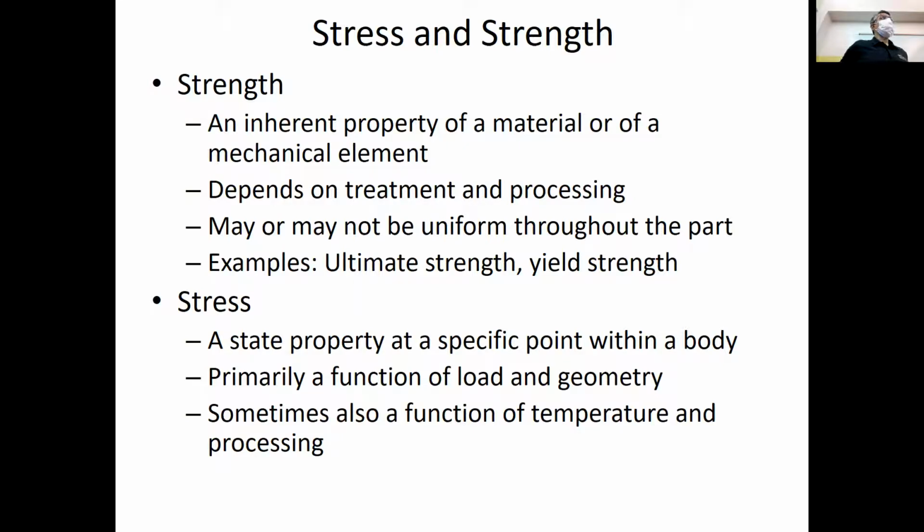On the contrary, a stress is applied at a point. A stress is related to the geometry and the load. If I increase the load, the stress is going to increase. If our part cannot handle that stress, for example, if it's a beam, I can reduce the stress by increasing the moment of inertia.